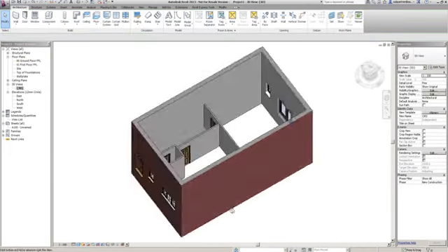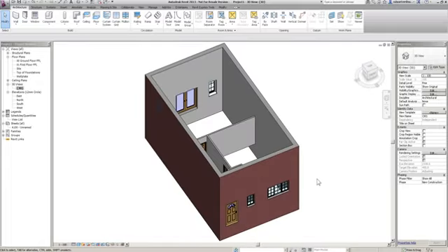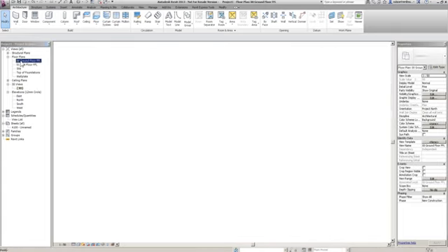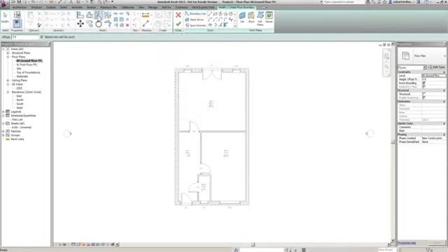As you can see, we're starting to build that up, but obviously because we're working on a BIM model, we're going to have to decide what's going on in the whole building, and we're not just talking about a floor plan here. We want to see what the floor constructions are going in here. So very quickly, I'm going to go back to my ground floor level, and I'm going to go to my floor tool. I'm going to choose a beam and block floor, and basically when you do a floor you have to draw a boundary and it will put a floor construction within the boundary.